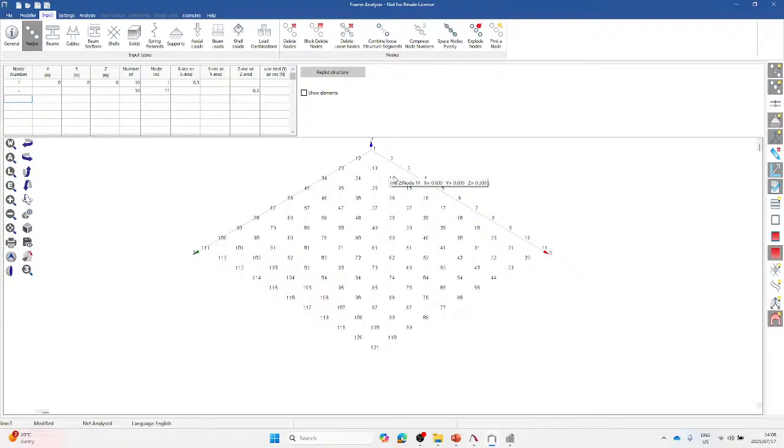Then to create the second set of coordinates for our model, we will definitely use the block copy function as well. So we will block copy line 1 and 2. How you know what line this is, at the bottom of your screen, it will show you line 1. And if I select that one, it will show line 2.